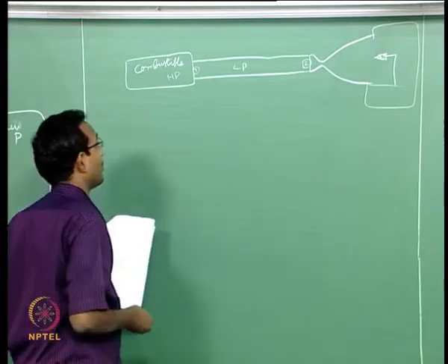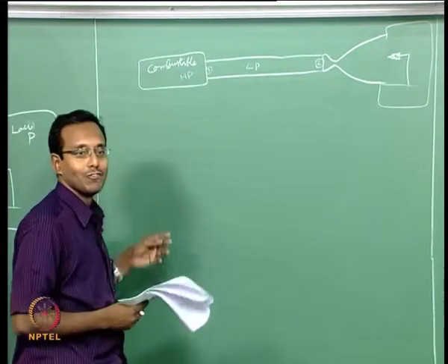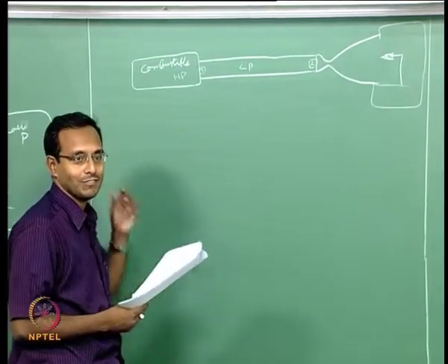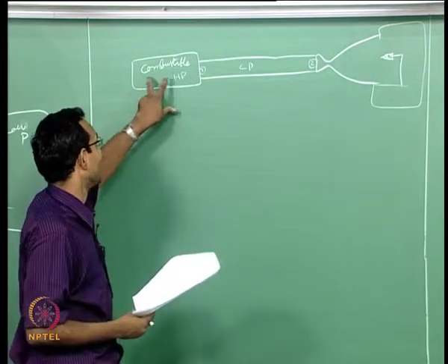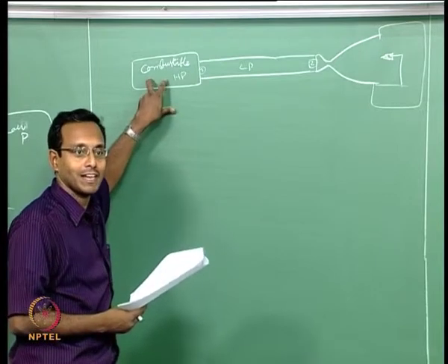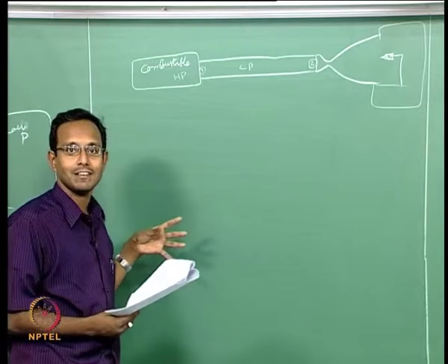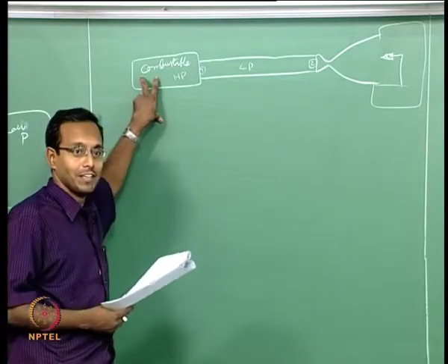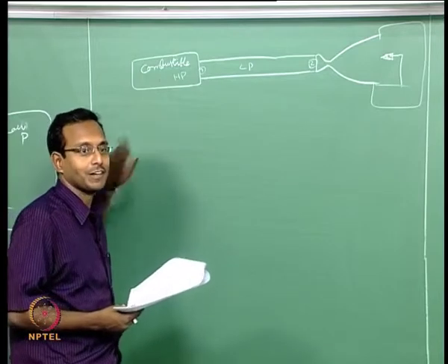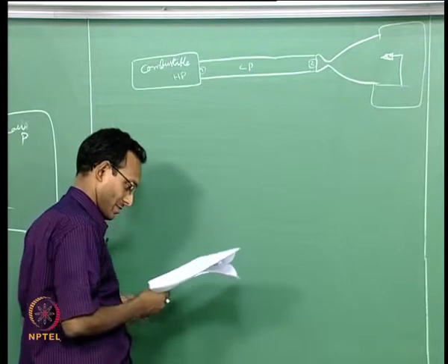Now if I think about what are the advantages of this, I can go for higher P naught and T naught with this for the same pressurization of the gases, because locally I can create even higher pressure than what I can get from tanks. If I get combustible mixtures in tanks, that will probably be 200 bar or whatever. Now this can be even higher if I want to create. That is an advantage here.